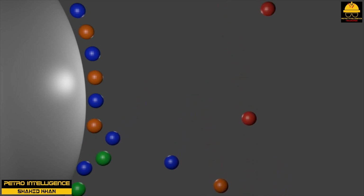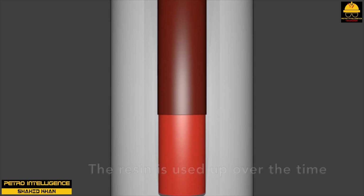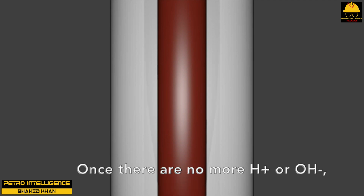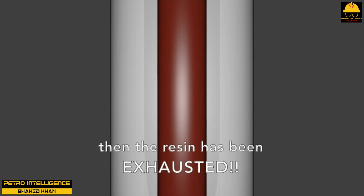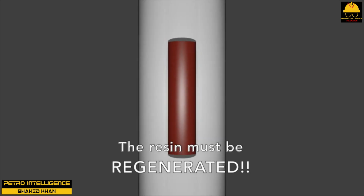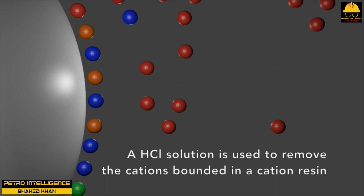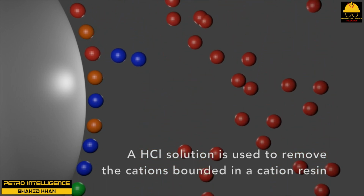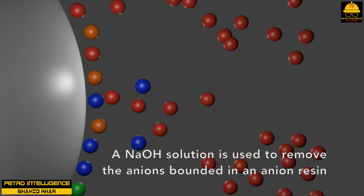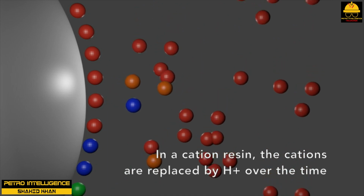Ion exchange resins are classified as cationic if they remove cations and anionic if they remove anions. In an ion exchange process, the process stream containing the impurities, which are in an ionized form, is passed through a bed of the ion exchange resins. Water treatment is a good example. Hard water contains salts of metals such as calcium, magnesium, or iron. Water treating resins have sodium ions active on their surfaces. The sodium ion replaces the hard ion; the latter remains attached to the surface of the resin bead.